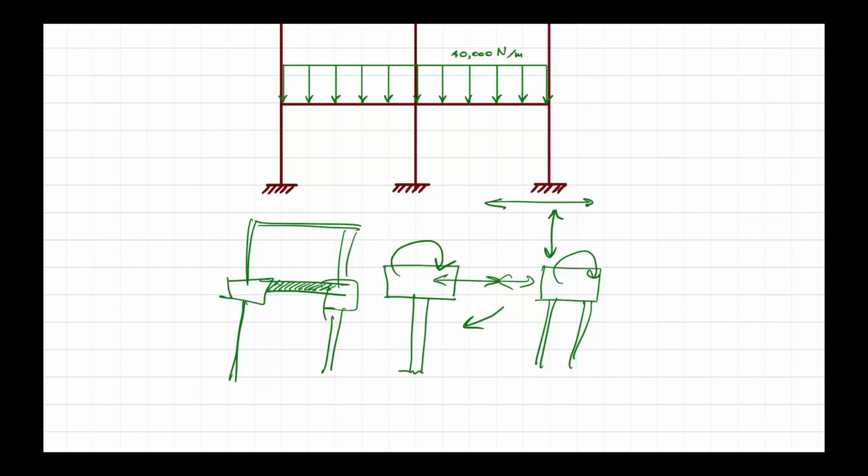But the ground beam is designed to be big in order to restrain the pile head, the foundation, against rotation and against relative displacement. When it is connected together throughout the building, that gives rigidity to the foundation, and then your assumption that the support is a perfect fixed support can be applied. The thing is that you analyze this way. When you design, you have to make sure that your structure behaves the same way as your structural analysis model. If you design the pin, make sure that it's going to be the pin.